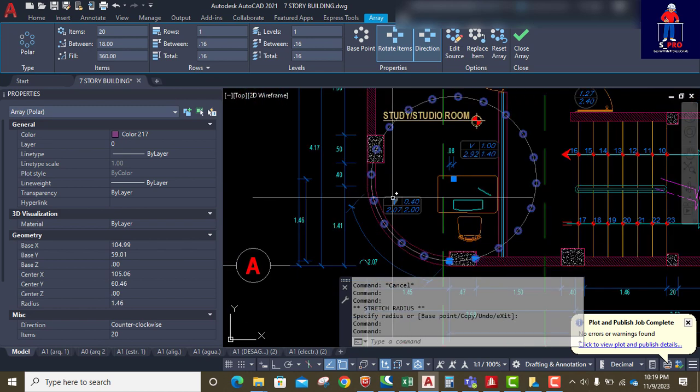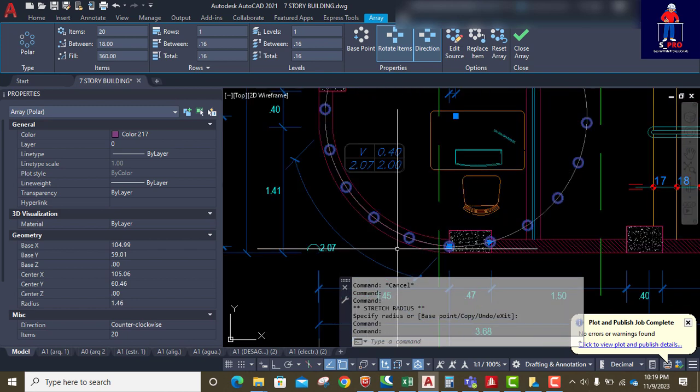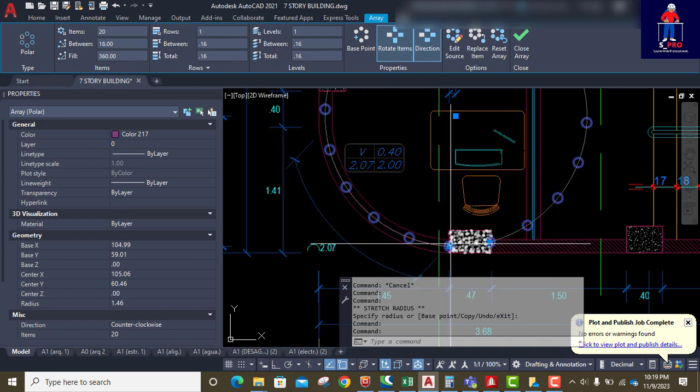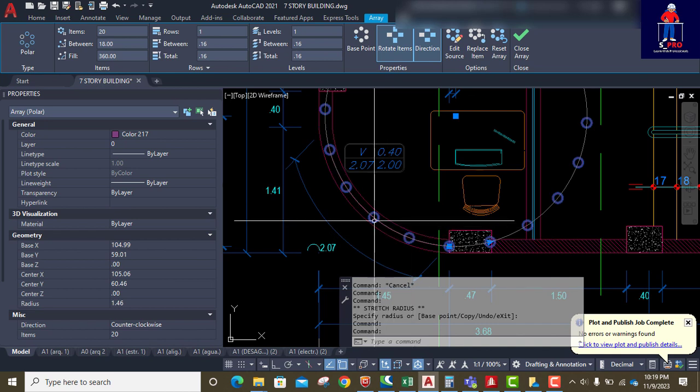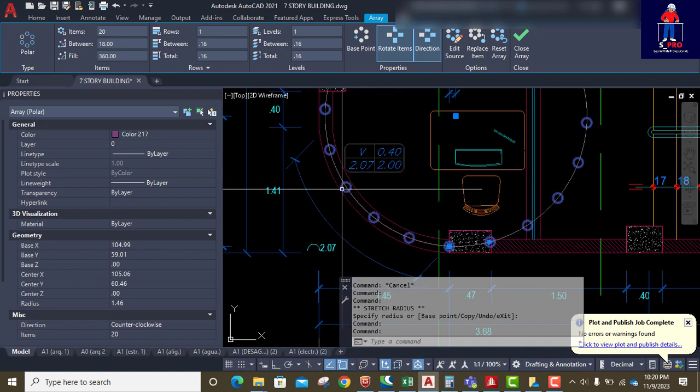So I have more points. I'm going to use these points to model these nodes. I have this one, which is already existing. So I'm going to model 1, 2, 3, 4. These 4 nodes. We already have a node in the model. So once I get these nodes on my model, I'm going to use a normal line to join them. So the more nodes you get will give you a more gentle arc. So when you create more nodes, you get a more gentle arc.